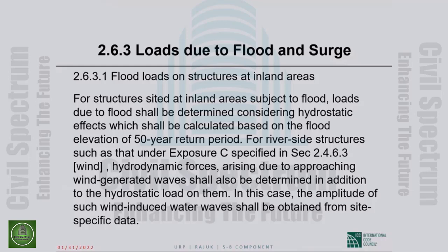To be classified as coastal risk area, the principal source of flooding must be sea tides, storm surge, and not riverine flood. Okay, it has to come from the ocean, not the river. The RA risk area extends from the coastline to an inland limit up to which surge water can reach. So risk area is all the area that can be covered by surge water.